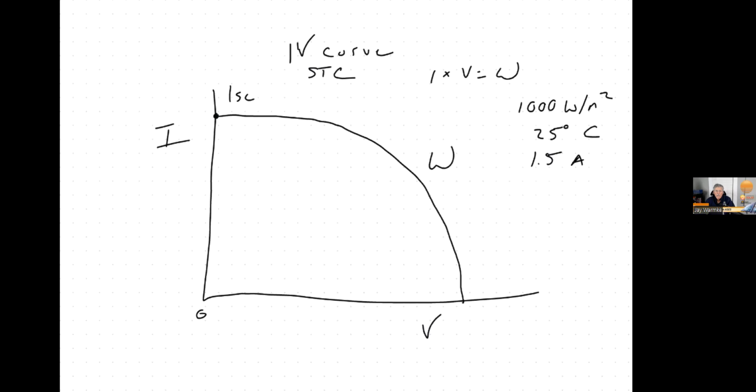The maximum theoretical voltage that panel might ever produce under standard test conditions is down here on this point, and that's known as the VOC. Now, the VOC we can actually measure. If you stuck a meter into a panel that wasn't hooked up to anything, you're going to be measuring VOC. Whatever it's generating in volts, you're generating it, and you're measuring it.